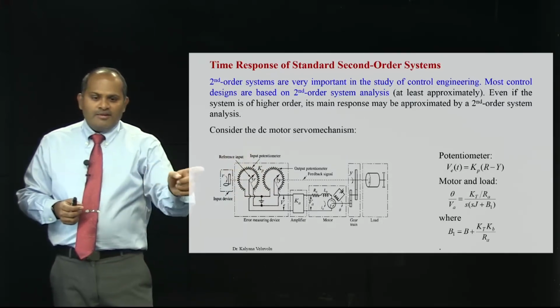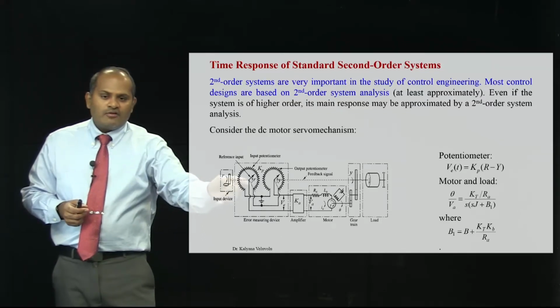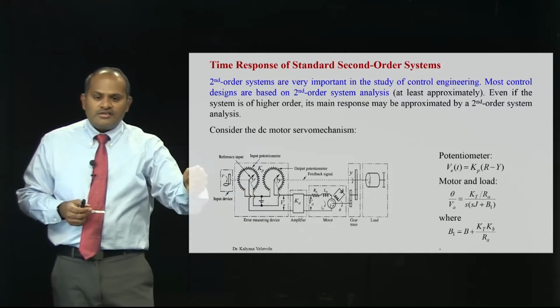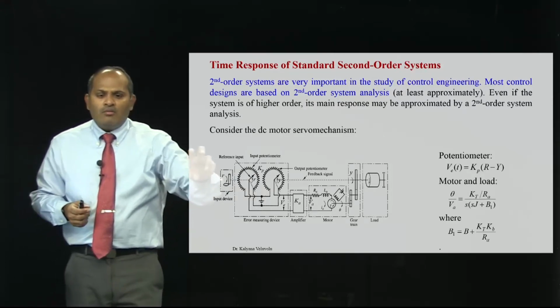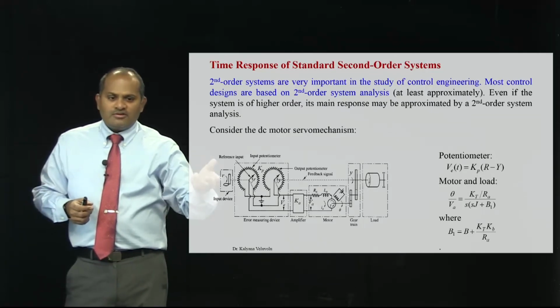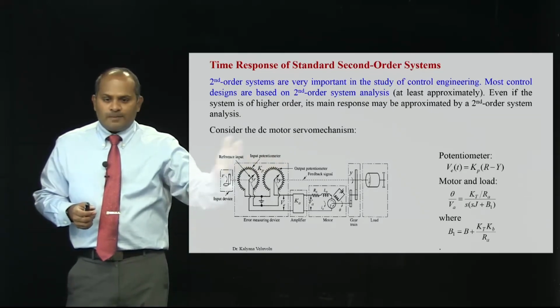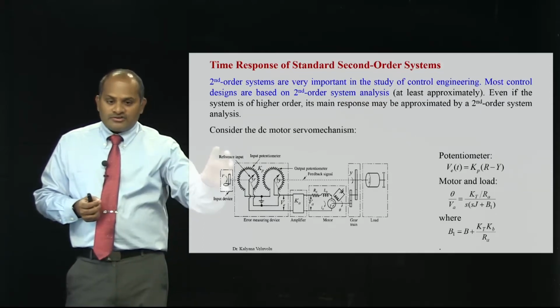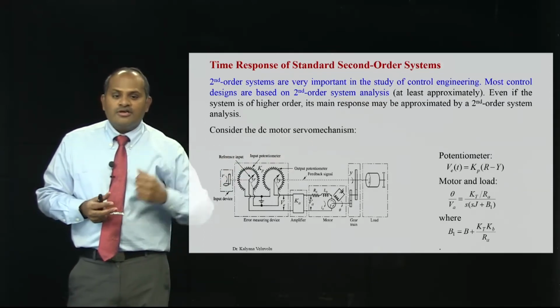The input is also connected to a potentiometer. If I rotate the input device, I can manually set the reference voltage. This reference voltage corresponds to the output speed. So we can calibrate the speed and then use this voltage as a reference to do speed control.